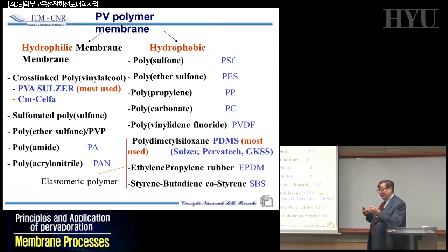So you have to optimize the system to have high solubility of these components in the polymeric phase without destroying mechanical properties. That's why, in many cases, you will find this cross-link term. That means you can find a way to increase the amount of your permeate that can be dissolved in the system without changing mechanical properties.